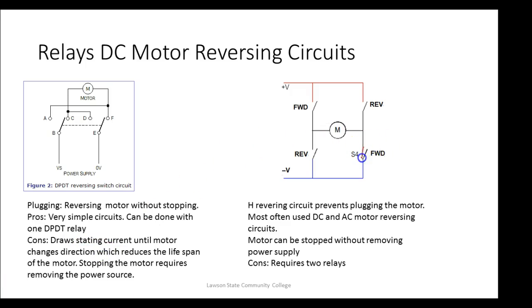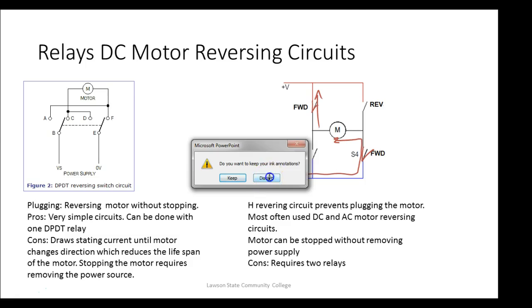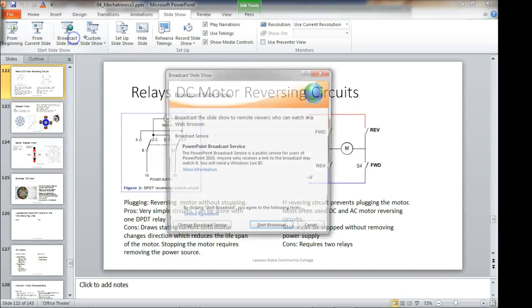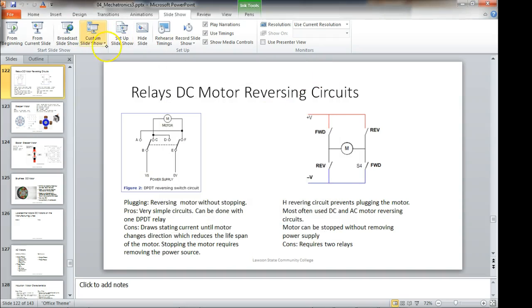But look, if we close this switch and we close this switch, then how would the current flow? Then the current would flow up and would go through the motor in this direction, right? Y'all see that? And then if I wanted to stop it, what would I do? I would just open up both of them. That makes sense? And the motor would do what? That would be able to come to a stop. That's probably the easiest way to do it.